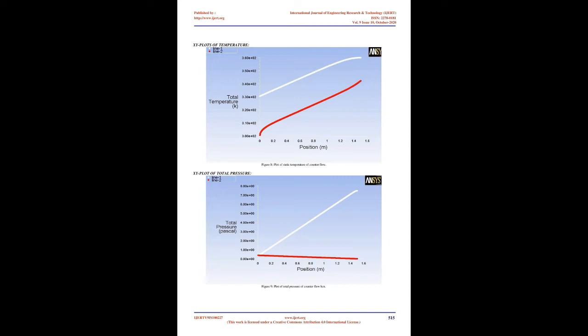4.1. Geometry. The heat exchanger is built in the ANSYS Workbench design module. It is a counterflow heat exchanger. First, the Fluid Flow (Fluent) module from the workbench is selected. The Design Modeler opens as a new window when the geometry is double-clicked.